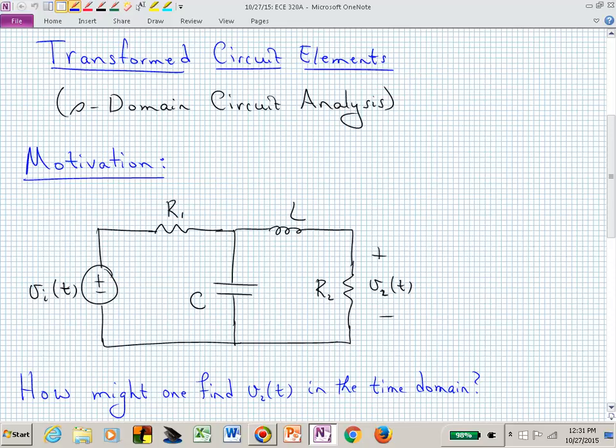And it will depend on these values of the R's and the L's and the C's as to where those 2 poles might be, whether they're 2 real poles or 2 complex conjugate poles. Where are the poles going to be in this circuit? Can you say right half plane, imaginary axis, or left half plane just by seeing this circuit? If somebody gave that question to you on an interview, could you tell them, is this circuit stable? Are the poles in the left half plane? That's an equivalent question. Can you make that statement now without knowing any values on the R's, L's, and C's?